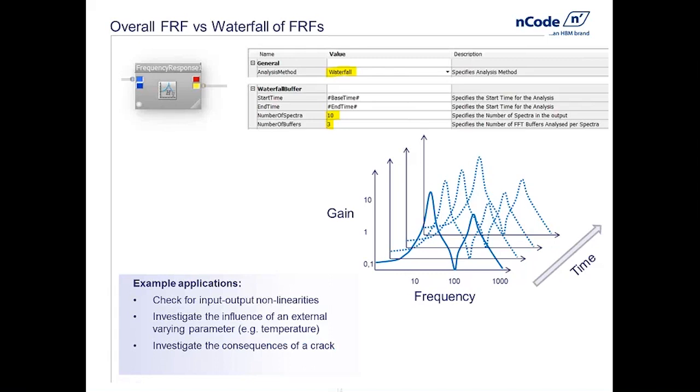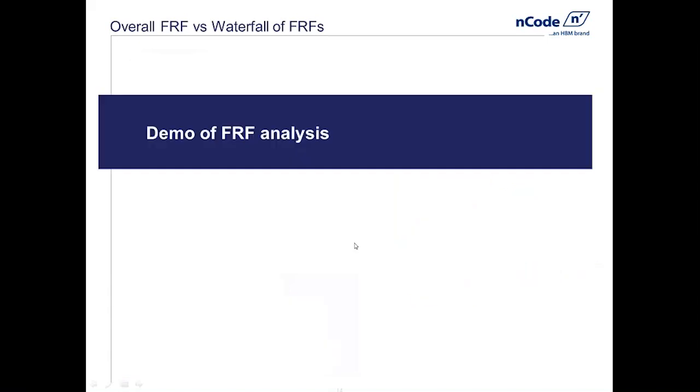And so again, the FRF would see maybe its dominant frequencies shift with time, with the appearance of a crack. Another application is some materials soften or harden when they are subjected to vibrations, to cycles. So that would be very easily observed with this new FRF versus time display.